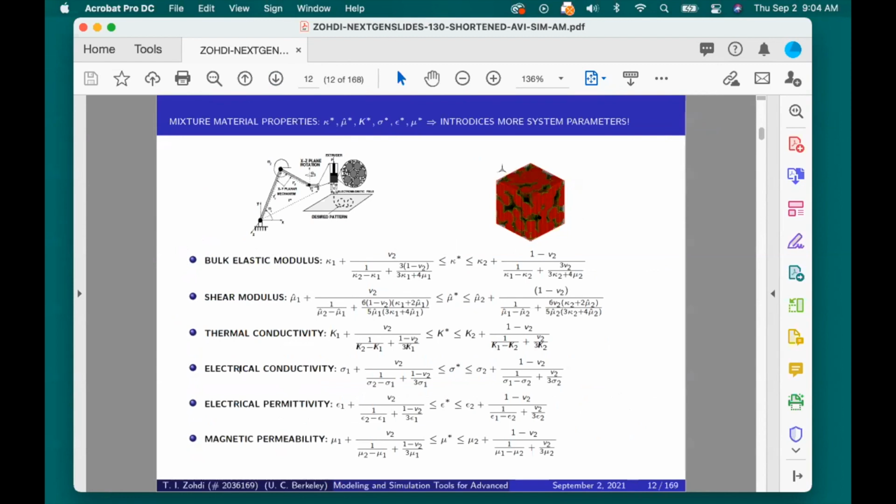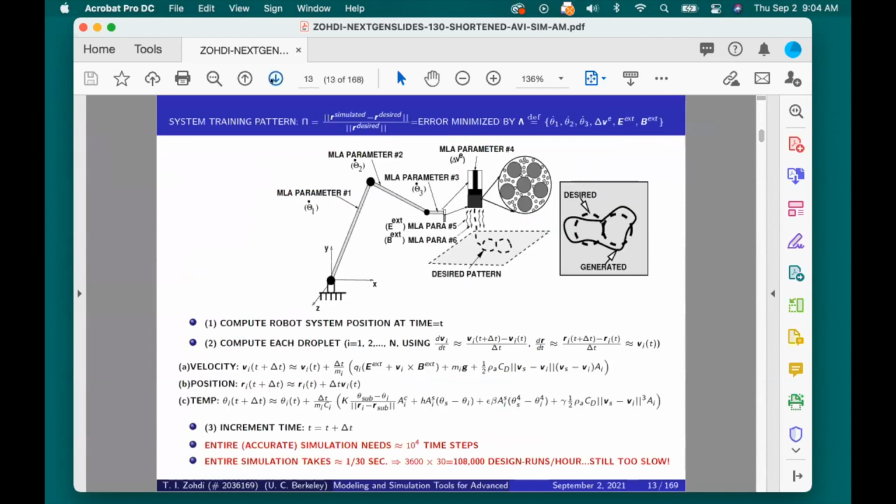The other approach, which makes, of course, the simulation slower, is to voxelize everything that gets deposited and essentially treat it as three-dimensional voxels. That's still rather fast, actually much faster than classical finite elements, but of course will slow down the processes somewhat. So usually what we do is we run the simulators with the Hashin-Shtrikman bounds first. Once we home in on optimal types of states, or what we believe are optimal states, we'll usually switch to a voxel analysis to compute what's going on.